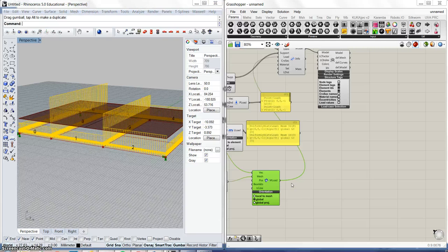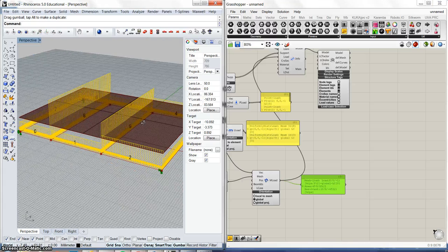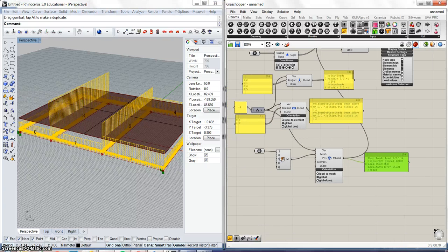And now, the way that this mesh load works is that it's a distributed load. I think that mesh loads are really valuable in general because if you were building a building and having a floor, you would have a load that was distributed over the entirety of that floor. And if you then wanted to figure out how it was falling on different beams, the mesh load simulates that really nicely. You don't have to continually calculate. It's automatically doing tributary areas, which is great. And this is where the setup of your divisions in your mesh matters.